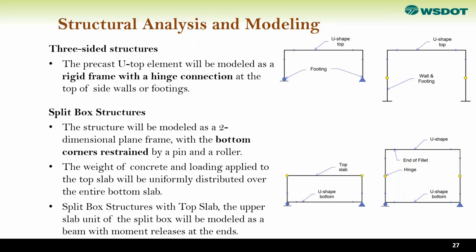One last slide on design is the modeling of these things. So this is again buried structures. We use a three-sided or a split box structure. In that case, we have a rigid frame with hinge connection at the top of side walls or the footing. So this is the roller and fixed connection in order to get the global stability in the design. And then a split box